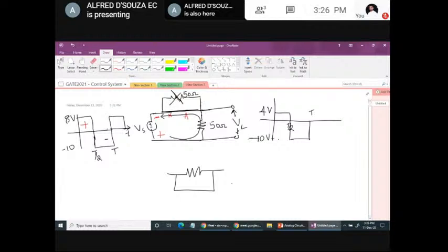We are supposed to find the average DC voltage. So how to find average DC voltage? You will have to integrate this entire waveform starting from 0. So this is V naught of t. You'll have to integrate this waveform from 0 to one complete period. Integrate V naught of t with respect to t and divide it by the period T. So this is how we are supposed to calculate the average or the DC voltage, but do not integrate. It is very time consuming.